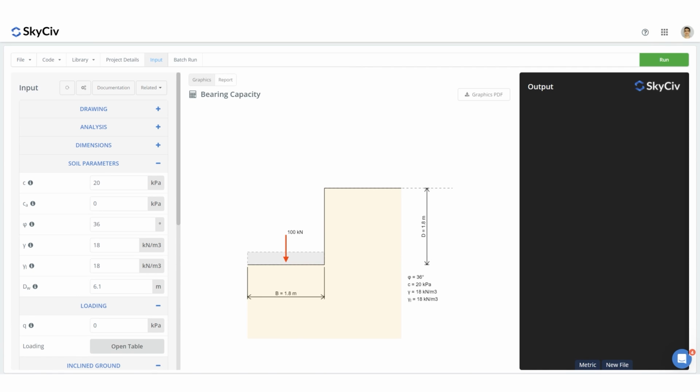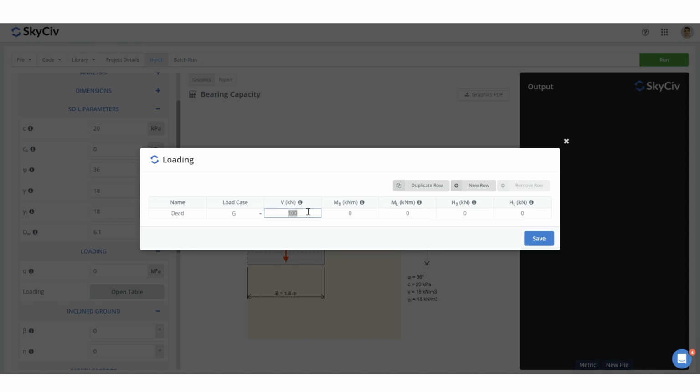We're also told that for design loads, we have a 1800 kN load. The design case that we assign is not going to matter because it's not going to be factored in this calculator. And we're told that we have two moments. We have a moment about x of 450 kNm and a moment about y of 360 kNm. Because we have the square footing, it's almost arbitrary which direction we put it in. But we're going to see in the calculator what happens with these two values and if they should have been switched.